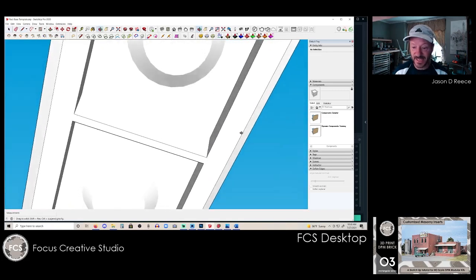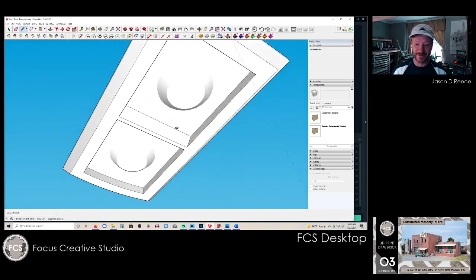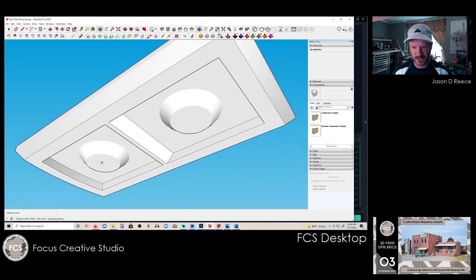Sometimes this is hidden geometry when it uses the bevel corner. And all I've done is basically solidify the geometry so it's no longer hidden. So like this, there's no hard edge. The model still sees it, but it can complicate things with reverse faces if you haven't modeled enough and you're new to this. But anyhow, so now as this pulls out of the resin each time, it's going left to right. So this is dipping in the resin, pulls out to the right. That resin is constantly draining off these surfaces.